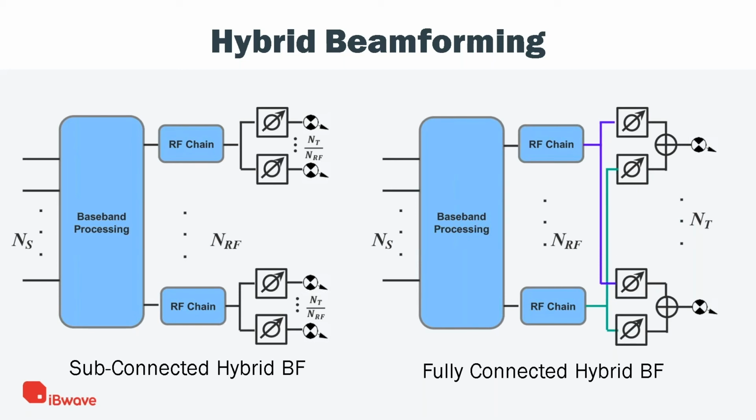And in the industry, what we have seen so far is more this type of application, especially in massive antenna arrays, where you have a very high number of antenna elements. Imagine that you have an 8x8 antenna array with cross-polarized antennas, which will be 64 to 128 antenna elements. Imagine that in a purely digital implementation, you would need 128 RF chains, one for each antenna element, which is very complex to accomplish and to implement.